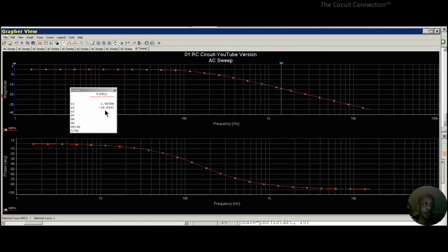You see how you get like negative 18 dB, and as you get closer to 0, we didn't go all the way down to 0, but you're talking about getting so close to 0, negative 432 micro, that's basically where you're at from 0 for these really low frequencies. And 0, again, corresponds to a magnitude of unity between input and output magnitude. In other words, you input a 1, you get out a 1. You don't get attenuation and you don't get a boost. You don't get gain. Okay, I guess that's enough said about that.